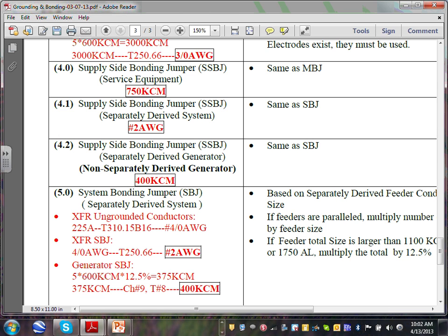See what I mean? So if you run EMT between the transformer and the panel, hypothetically, then you go into the methods of bonding at the surface. The conduit matches the hole, with tight locknuts on both ends, or a wedge, or a bonding bushing, and you do not need a wire.